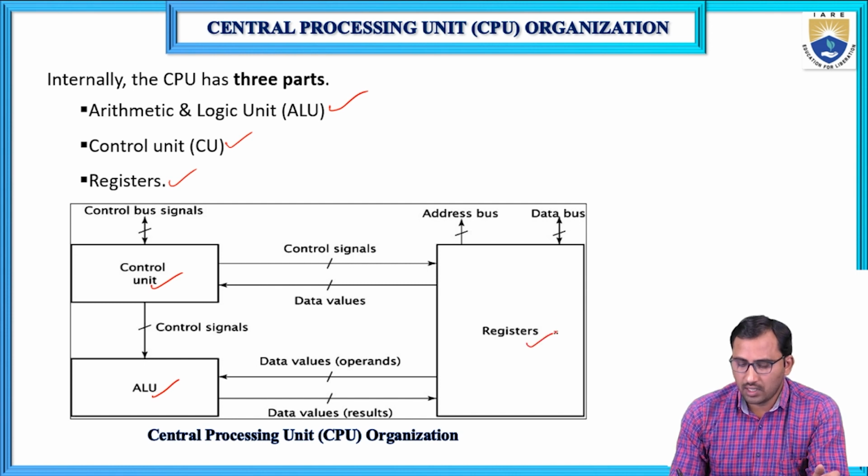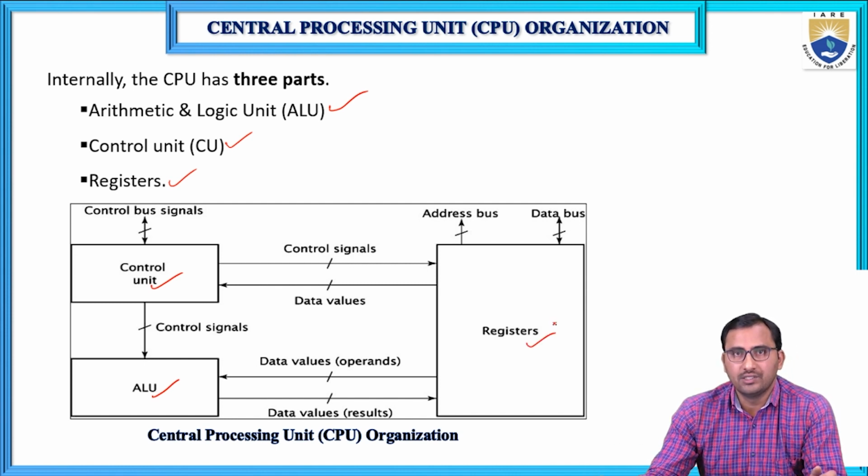The third one is the internal registers. Already we know the registers are used to store information or data. A register is a group of flip-flops. A flip-flop is a single-bit storage element, so using a flip-flop we can store either 1 or 0. A group of such flip-flops is called a register.